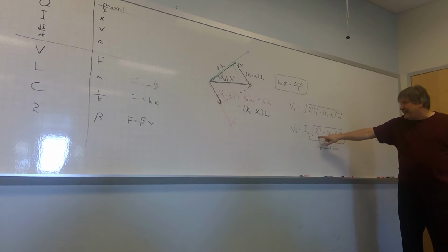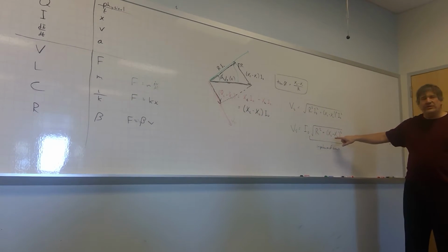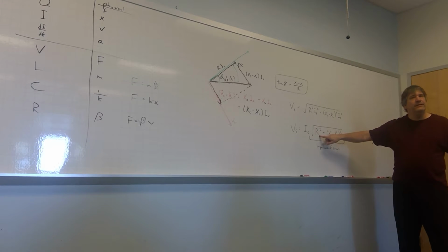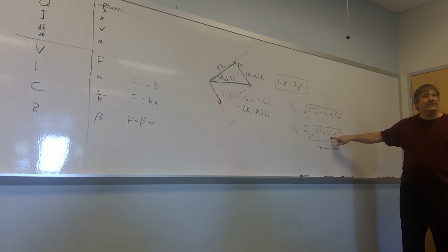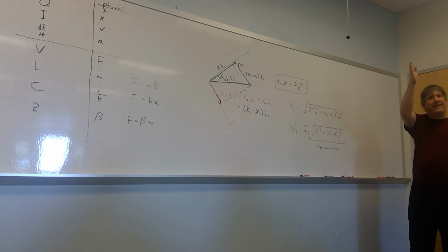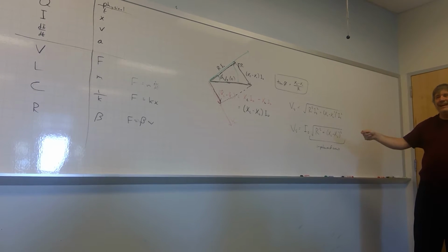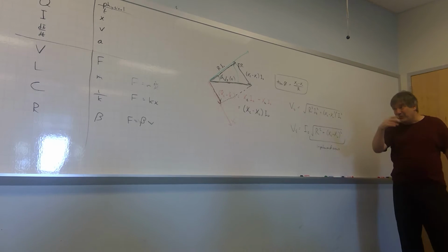on this right-hand side of the equation, what's going to be changing under the radical sign? Is the resistance going to change? No. Is the impedance of the capacitor going to change? Yes. As I raise the frequency, the impedance of the capacitor will go down. Is the impedance of the inductor going to change? Yes, as I raise the frequency, the impedance of the inductor will go up.